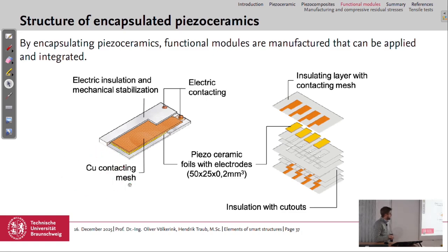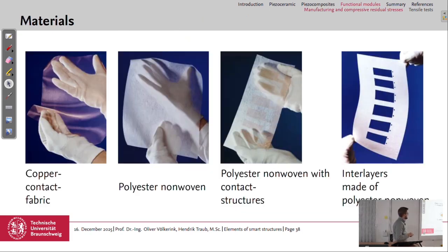a copper mesh. And it's done in a way that we stack non-woven glass fibers, for example, as spacing layers where the cutout is in for the piezocomposites, and where the copper meshes are applied to contact the electrodes.